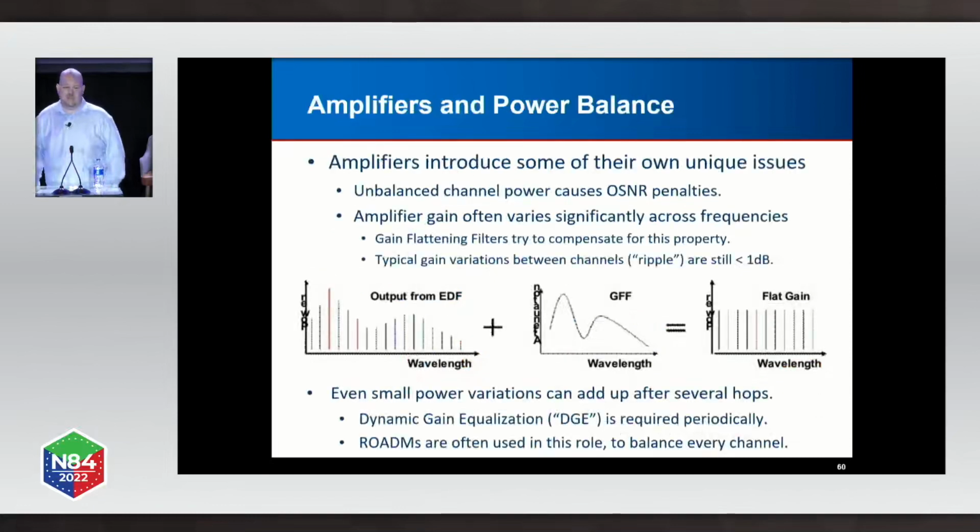But when you do amplification, you really have to concern yourself with power balance, because with amplifiers, the whole point of what you're doing is you have all these channels, and they, to some degree, have to be balanced. If they're not balanced, what happens is the high power channel steals all the power, and the low power channel doesn't get any. So it's actually a problem, and one of the reasons that you can't just sell spectrum is if someone comes along and injects a signal, a really bright signal that you don't want, it'll just destroy all of your good signals. So you have to look at this.